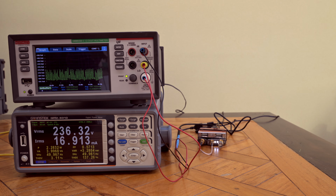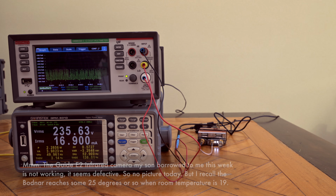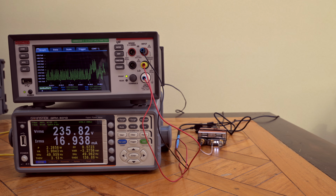I also see that the unit is getting mildly warm with continuous use. I will use a temperature meter, so we're going to see a bit how warm it's getting. But anyway, I might not be powering this unit all the time, maybe only when the lab is on, because it seems to lock quite fast. I have to look a little bit more into this. But if the PLL lock is actually as fast as it seems to be, there's no need anymore to have it on 24/7. And then power consumption is not much of a concern on my side anymore. And it increases the lifetime of the device as well, I would expect.